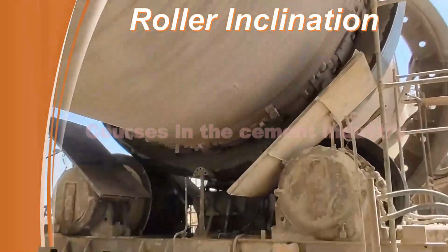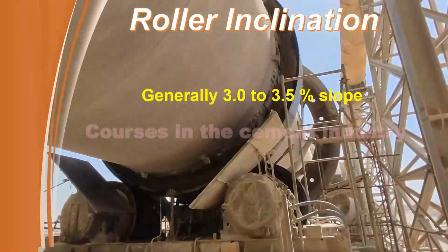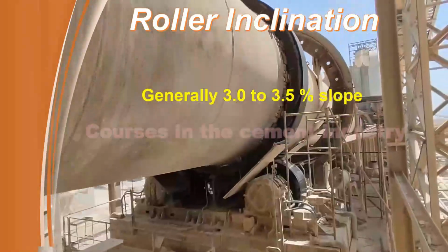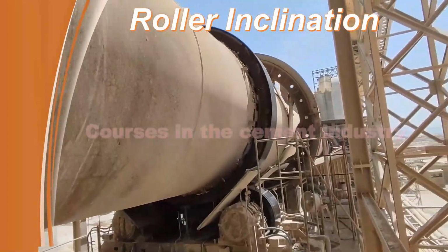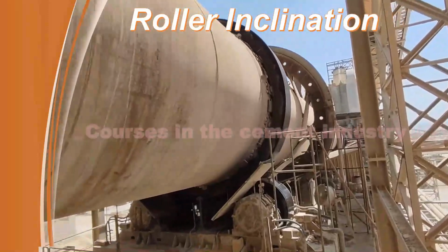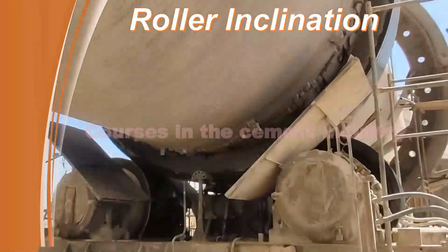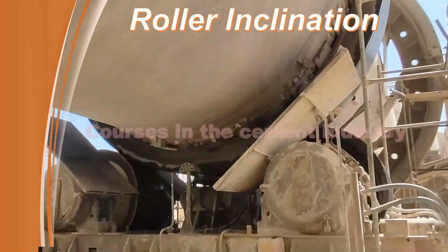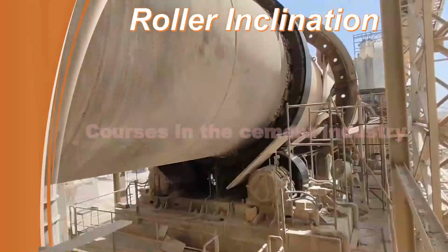The kiln is kept inclined, generally 3.0 to 3.5% slope, and rotating in order to convey material from the feed end to the discharge end. In case the kiln has no slope or is horizontal, the material will not move further and will get accumulated at the kiln inlet only.